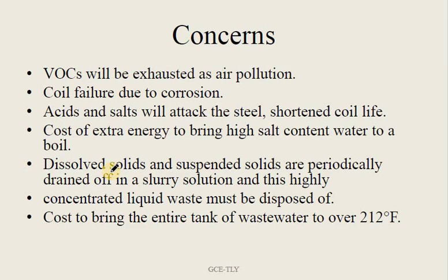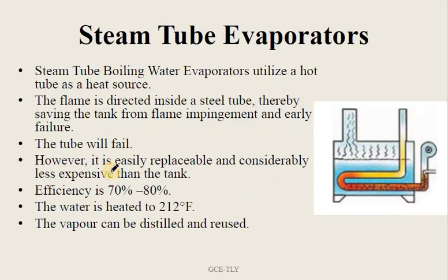VOC problem will be there, and there may be coil failure due to corrosion, and acid and salt attack may be still there. There may be extra energy required for high salt content if present in wastewater. And the same dissolved solids and suspended solids need to be drained off periodically. So that wastewater disposal will be a problem. Then the cost for heating the entire tank is also there, so extra care should be given to that.